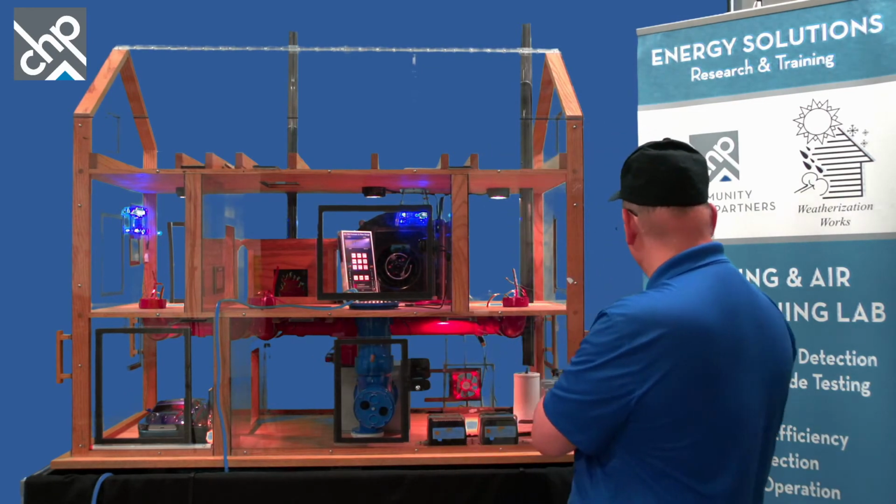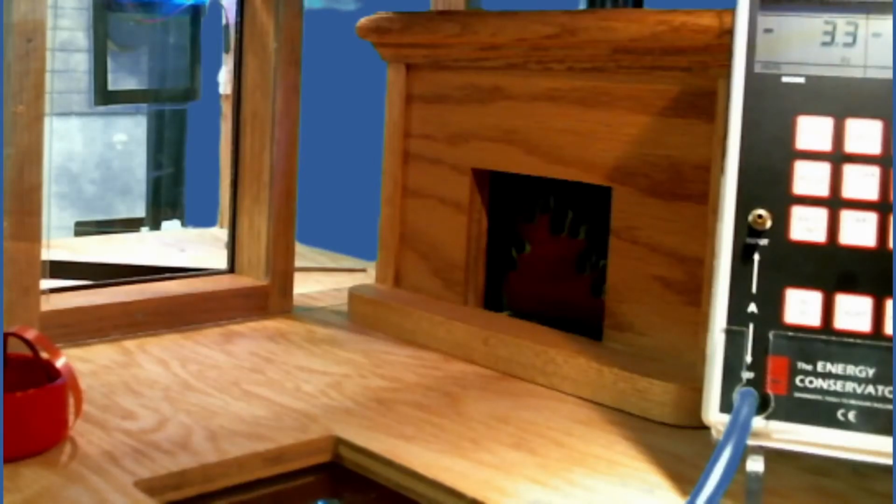And you can see the number there where we're at now is at -3. So the next move is, in this case, our CAZ is in the main central part of the house, but occasionally, well, not occasionally, actually a lot of times, you'll have a CAZ in a mechanical room or something with a door. What we typically do is test once with that door open and once with it closed, and record both of those numbers with the exhaust fans on.